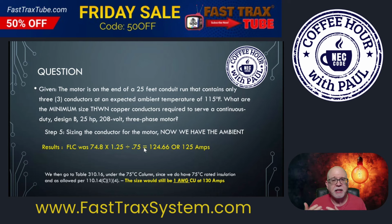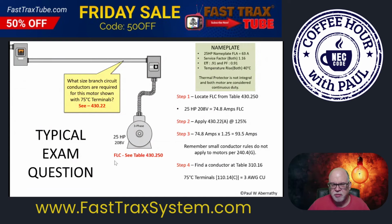So now if we were to look at this from an illustration point of view, remember what I said: if we did not have any ambient temperature in this equation. I tell you this one to be ready for exams, okay? If there was no question about ambient temperature or the number of current carrying conductors exceeded 3, then it's pretty straightforward, right? 74.8 amps came from the table. Then you apply the 125%.